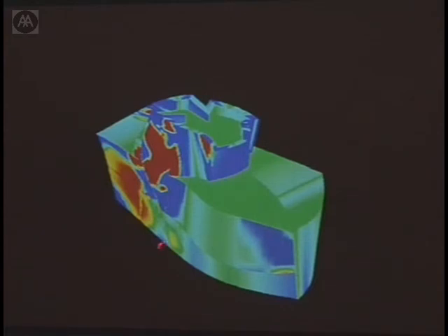So you put that into the system and analyze the surfaces, and wherever it's light blue and green, you know that the material will be able to take up just a little bit of warp. And where it becomes dark red or blue, the material can't do that anymore, and you would end up with this kind of crease situation.